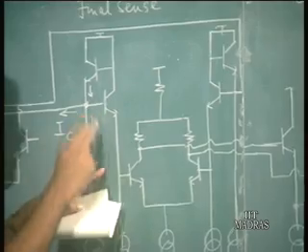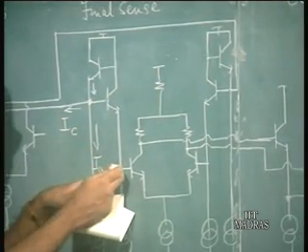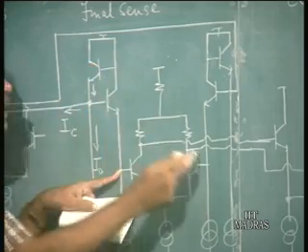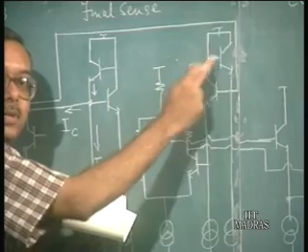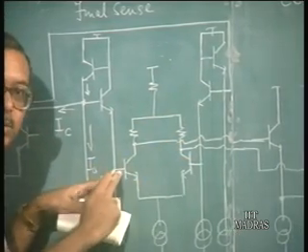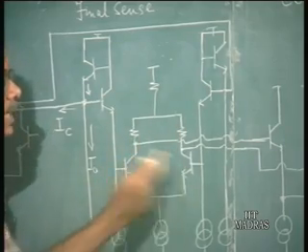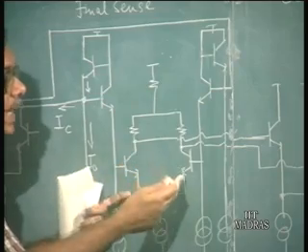Okay. So, here the base voltage depends on the VBE drop of this transistor, and the base voltage here depends on the VBE of this transistor. So, you have a difference in voltage between the two base voltages, which is then sensed because this is a differential amplifier. Any difference in base voltage will result in a difference in current. This is nothing but an ECL stage, you see.